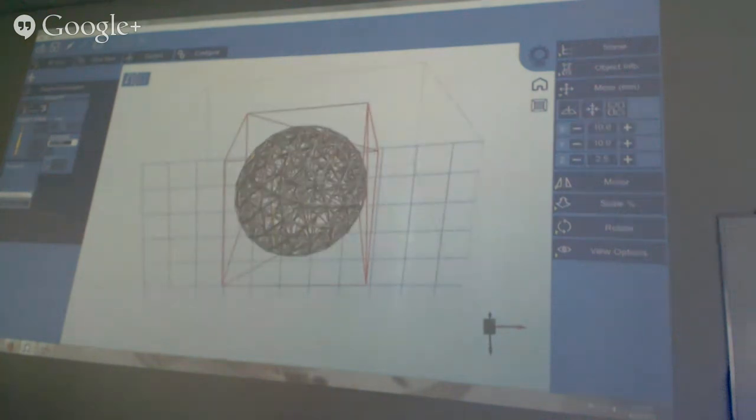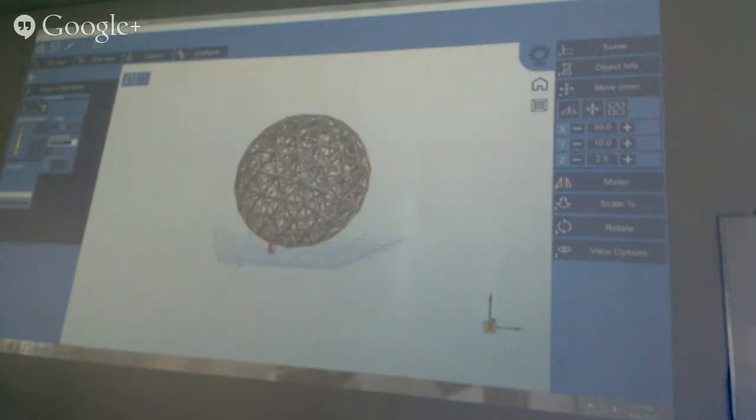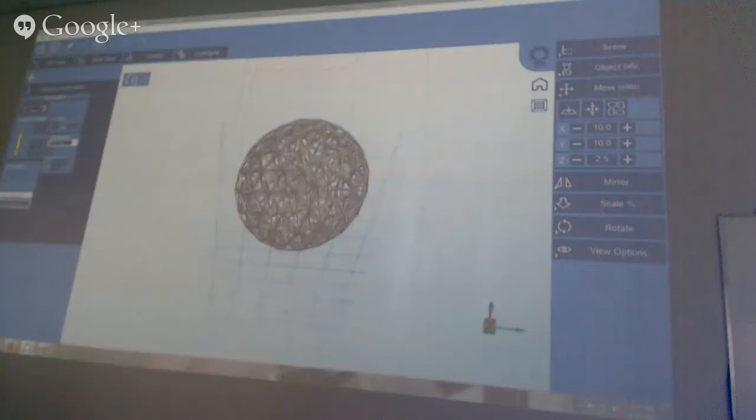So for example, this is for manual support, and then we click it. It should give you a support at the specific location here. And this newer version of Creation Workshop will give you a bent support instead of a straight one. We could add another one.